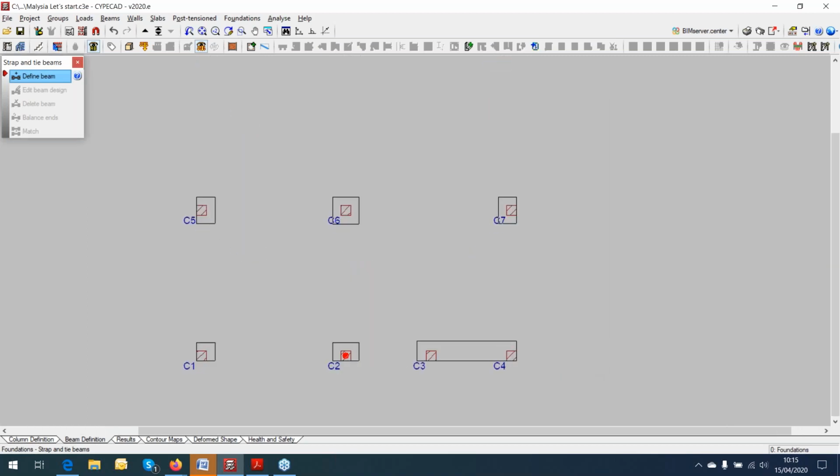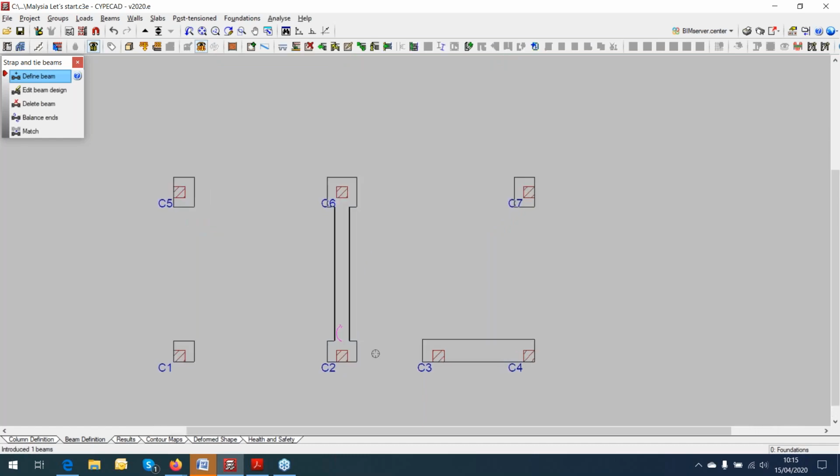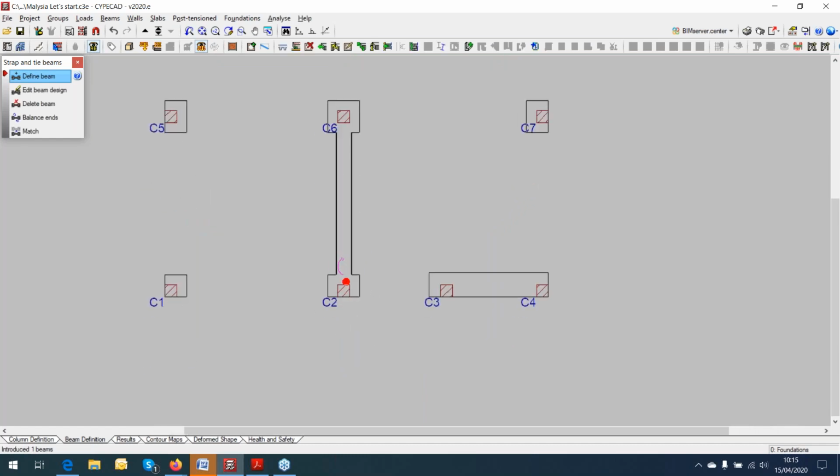And you see, if I go from the pillar number 2 to the center, the program automatically is going to select the moment. This is a small moment. It shows you that all the effort reaching the pile will be focused here. And the other part means that it is a center footing, and the program in this area is going to select the connecting beam or tie beam.